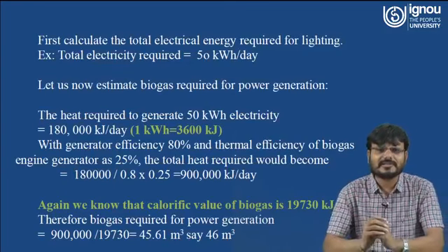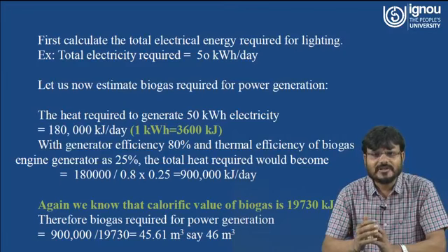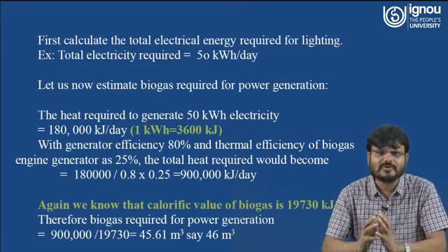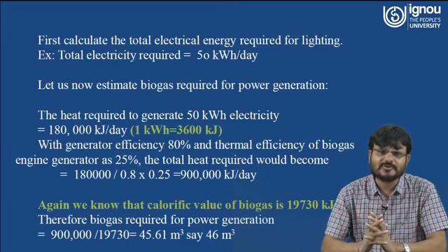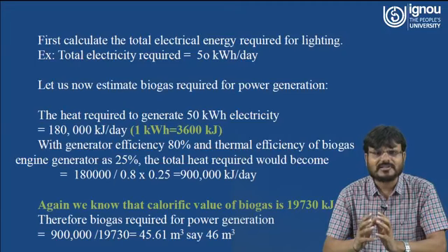Now again we can understand how the size of the biogas plant is decided, by the following points. First of all, you must know how much electrical energy you need. So first, you have to calculate the total electrical energy required for your house or for any purpose. How can the electrical energy be calculated? You know the wattage of all the appliances, and you know how much time you will use those appliances.